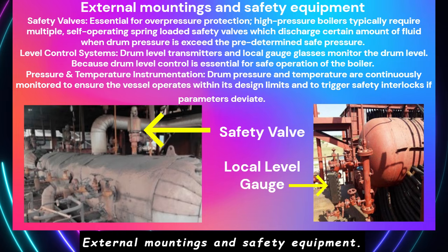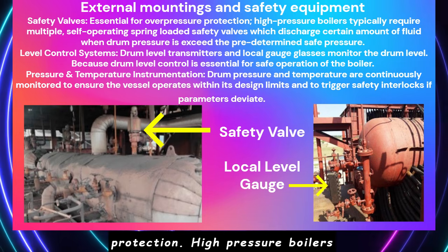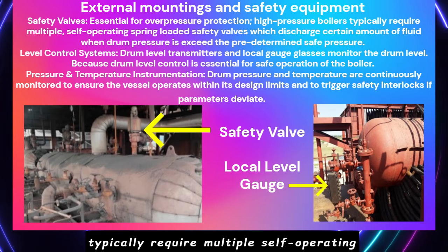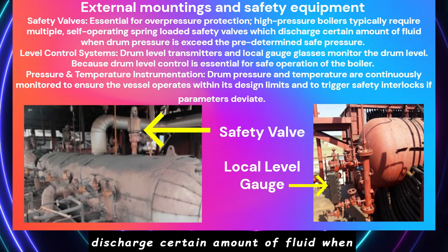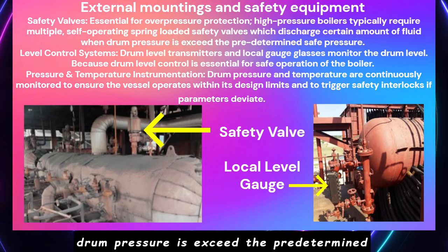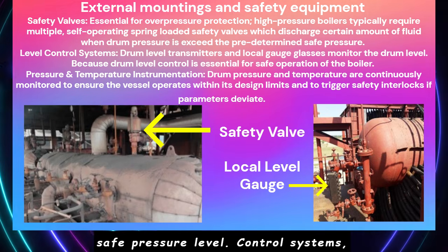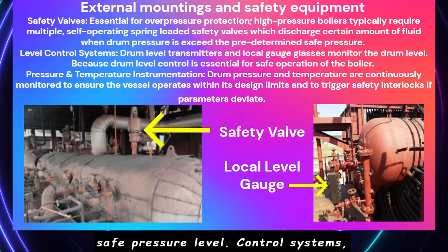External mountings and safety equipment. Safety valves, essential for overpressure protection. High-pressure boilers typically require multiple, self-operating spring-loaded safety valves which discharge a certain amount of fluid when drum pressure exceeds the predetermined safe pressure. Level control systems.